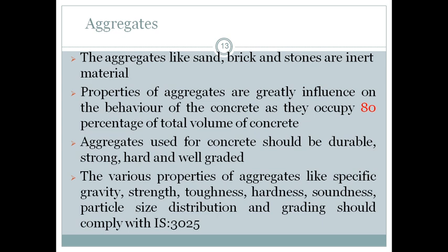The properties of aggregates greatly influence the behavior of concrete because they occupy 80% of the total volume of the concrete. That means the major portion of the concrete is occupied by coarse aggregate and fine aggregate, and almost 20% is occupied by water and cement.